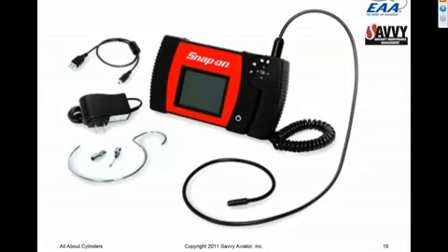The new trend in borescopes is the electronic videoscope, like this Snap-on. This is a BK6000. It's a nice scope, and it has a little camera, a little charge-coupled camera, a CCD camera, that's very, very tiny, and that we can insert into the cylinder through the top spark plug hole and take pictures. And we see the results on a little color display. There's a USB cable, so we can plug this thing into our laptop and capture images. You can actually capture stills or movies. There are some adapters. This particular probe has a 0-degree viewing angle, but there's a little 45-degree mirror adapter you can see in the middle left side of the slide that you clip on there if you want to get a 90-degree angle, which is what we usually do when we're looking at cylinders.